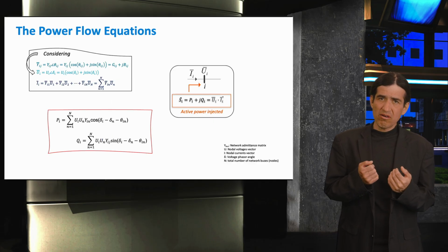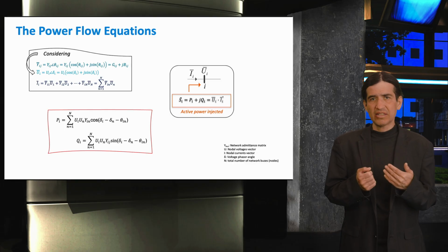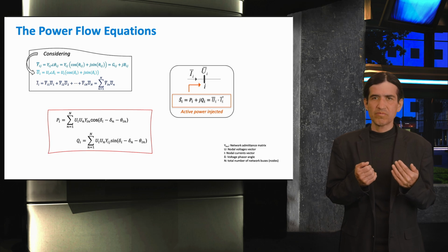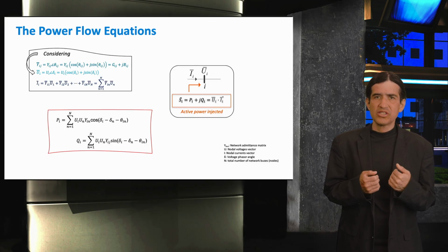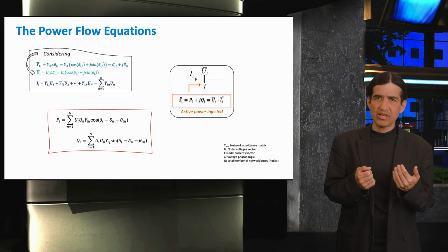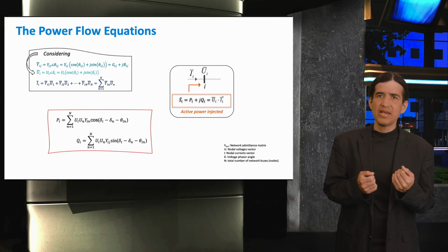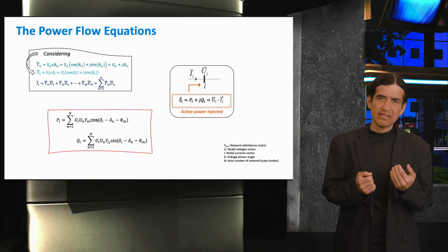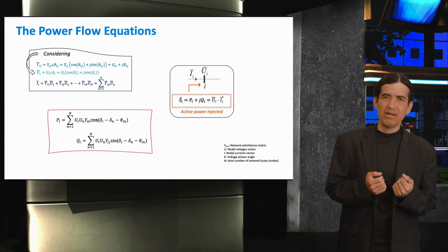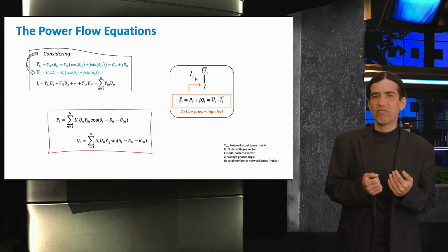The formulation of power flow calculation considers that active and reactive power injection equations are derived using the relationship between the Y-bus matrix, bus voltage phasors, and nodal currents, starting from the complex power at each bus, expressed as the product of voltage and current. So, substituting the current from the Y-bus relation and separating the real and imaginary parts gives the nonlinear equations for active and reactive power in terms of voltage magnitudes, angles, and Y-bus elements, which are then used to solve the power flow problem.